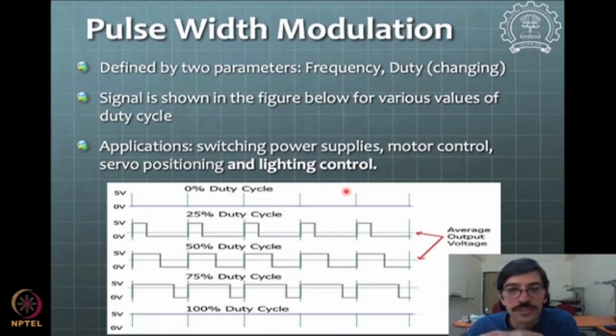During operation, if you want more power to be delivered, depending upon what your control input or control computation is, then you change this PWM duty cycle. You can see here the signals for different duty cycles and how they look. This is the 0 level and this is the 1 level, and here the on time is 75% of the total cycle time.